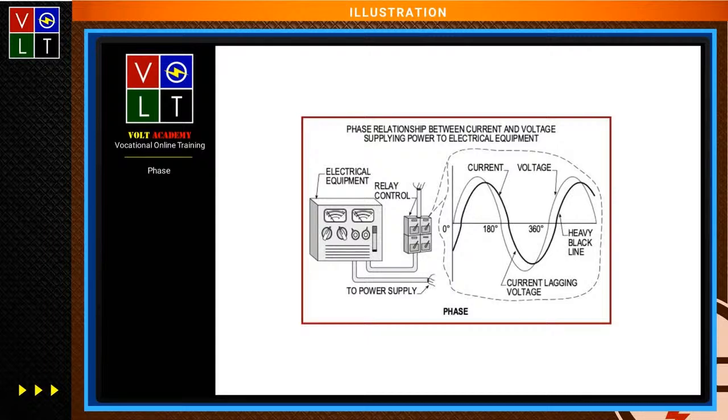Now, the next thing you're going to look at is the phase. The phase of the alternating current or voltage is an angular distance, where it has moved from 0 degrees in a positive direction. The phase angle is the difference of rotation between two alternating currents or voltages, or between a voltage and a current. As an example, when one voltage reaches a maximum value, say 30 degrees later than another, there's going to be a phase angle of 30 degrees between the voltages. Okay.